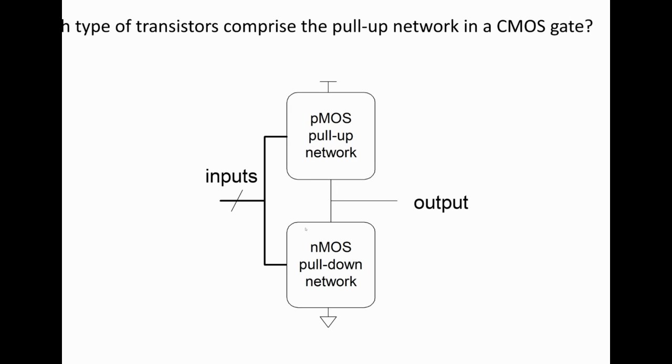So the amount of current is limited, but it's still not trivial. There's a lot of current that flows when you're at that halfway point between 0 and 1 on the input, and so that's where most of your energy is spent on a CMOS chip: during the transition, when the output transitions from 0 to 1 or 1 to 0.